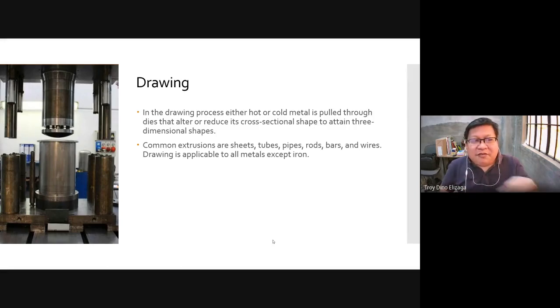When I chose this picture, I thought at first that he was trying to form a pot, but that's one product that can happen in drawing. For example, the pots for rice cookers are done by drawing. So you force it into a mold.